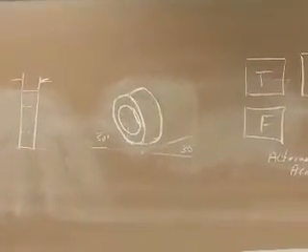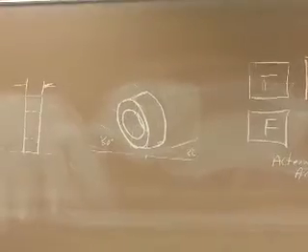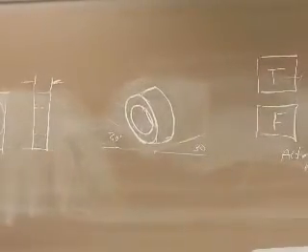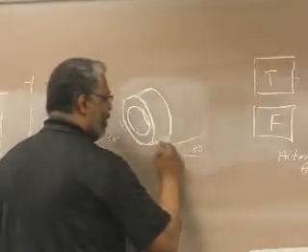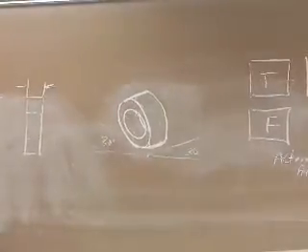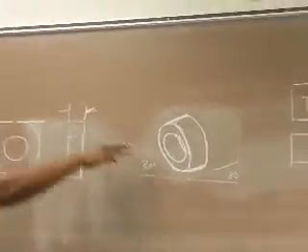Yes. A good rule of thumb is that the tangent lines on the sides of the circle should be parallel to each other. Yes. Yeah, these are going to be parallel to each other. Okay, so now that would be an isometric. And it's a little bit distorted, but anyway, you see the principle.